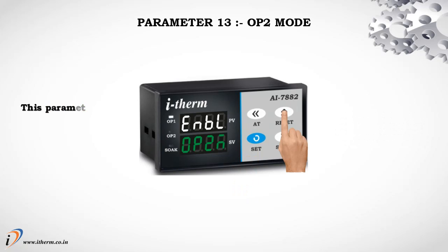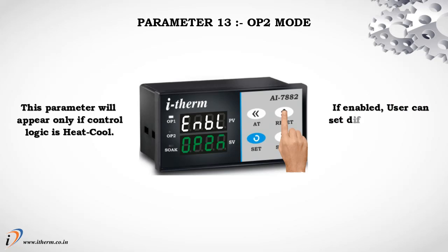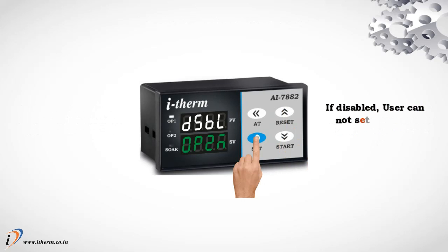Parameter 13, Output 2 mode. This parameter will appear only if the control logic is heat-cool. If enabled, the user can set a different mode for output 2 in the user list. If disabled, the user cannot set a different mode for output 2 in the user list.